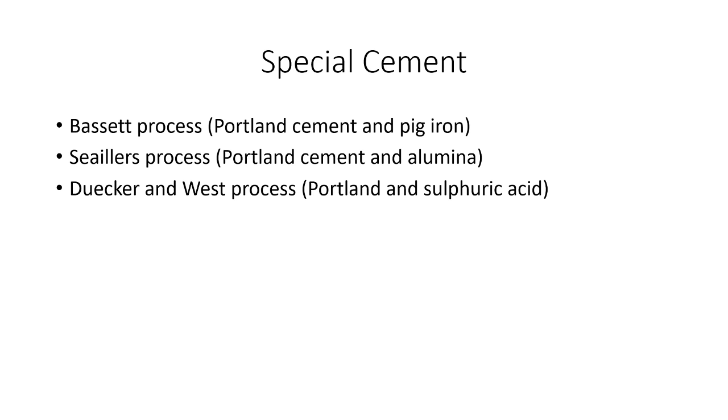Then next is the Muller-Kuhne process, Portland cement and sulfuric acid. So the raw material contains calcium sulfate, that is anhydrous gypsum, clay and coke together with sand and iron oxide. This mixture is burnt in a rotary kiln when sulfur dioxide is produced from calcium sulfate, and it is used to produce sulfuric acid as a byproduct. Means this is the third important byproduct, that is sulfuric acid, which can be obtained from sulfur dioxide gas and may be further converted into fertilizer grade ammonium sulfate.